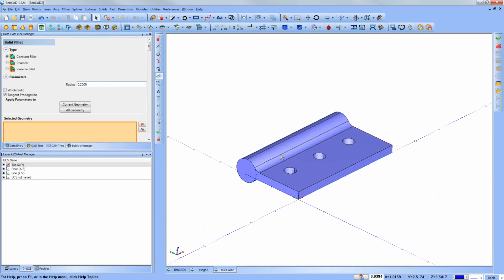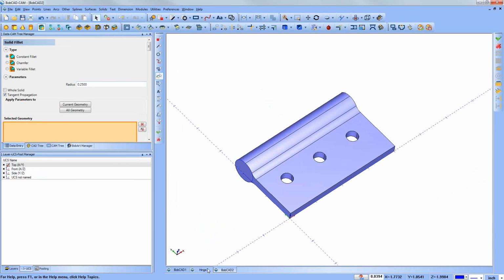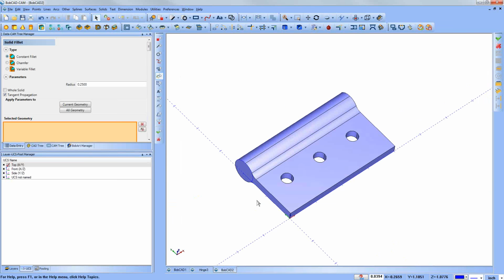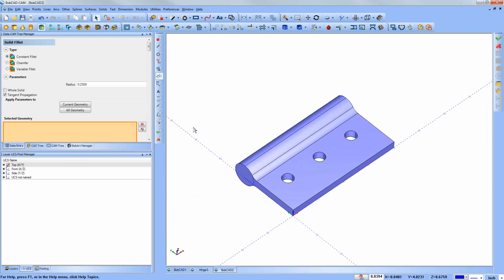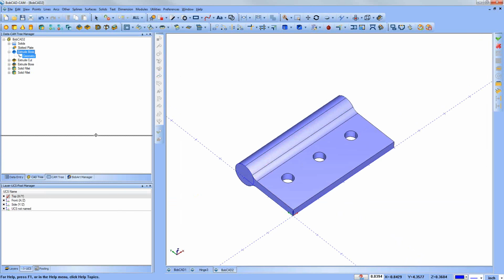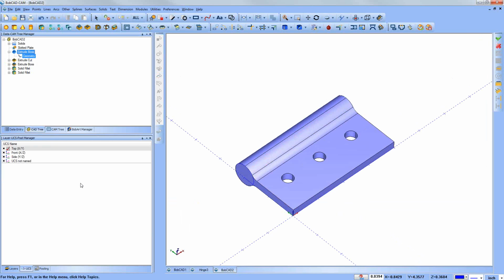And let's do some cutouts for the additional part on this hinge here. We have these cutouts, and then we have also obviously the bolt hole or the dowel that goes through to hold it in place. So looking back here, we'll go through the next step. Okay, let's cancel that out. So let's make another layer again, just to organize geometry and be able to isolate it. I'll call this cutout. We'll make that the active layer.